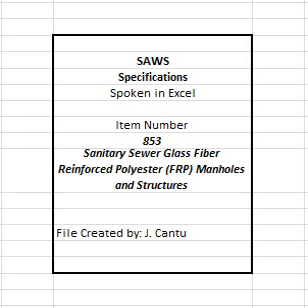All manholes/structures must pass a leakage test. A. The contractor shall perform the testing for all sanitary sewer structures in accordance with this specification, after assembly and final compaction backfill testing, for leakage, separate and independent of all other sanitary sewer piping, by means of either a hydrostatic test or vacuum test, or other methods approved by the engineer. B. Engineer of record must witness all tests over the EARZ.